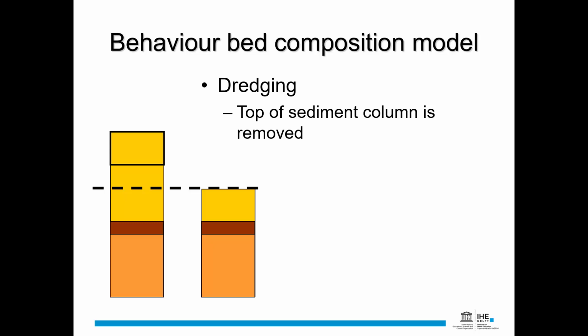If you are using the dredging option of Delft3D and you want to model the dredging, you should be aware that dredging always removes the top layer, whatever it is. So it doesn't matter what the mixture of the top layer is. It just takes that part out, and then the active layer will start in the next step from beneath the new bed level after dredging.